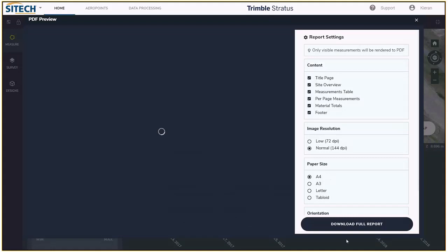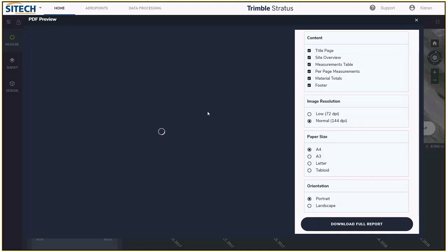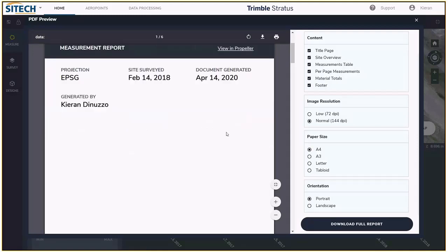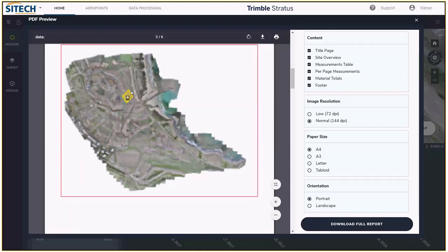And this is just a preview, but essentially we'll get a little bit of a basic formatting with that measurement that we've conducted before, that earthworks progress. So that'll give us our numbers that we saw there, so 33,000 cubic meters, and then whatever's left to the design. There's our little site map to show the context of where I drew that boundary.